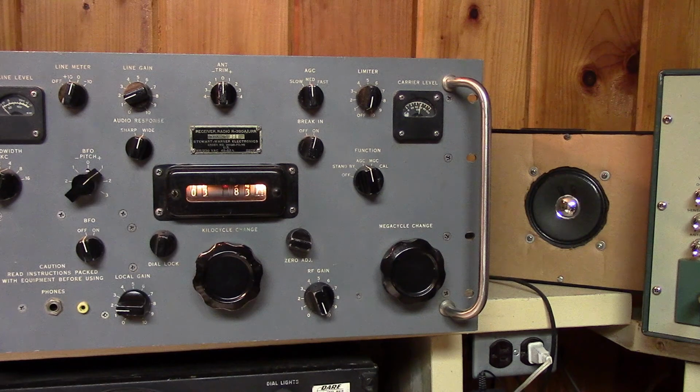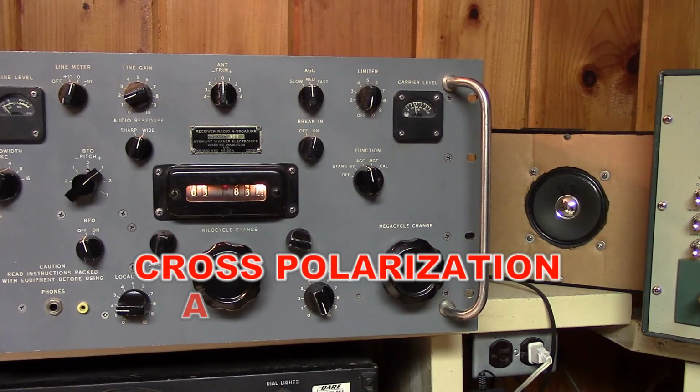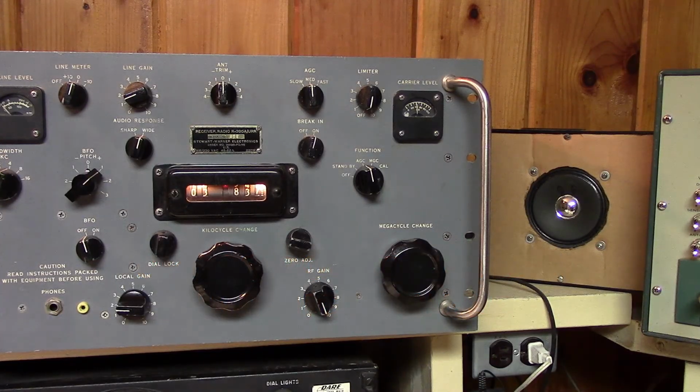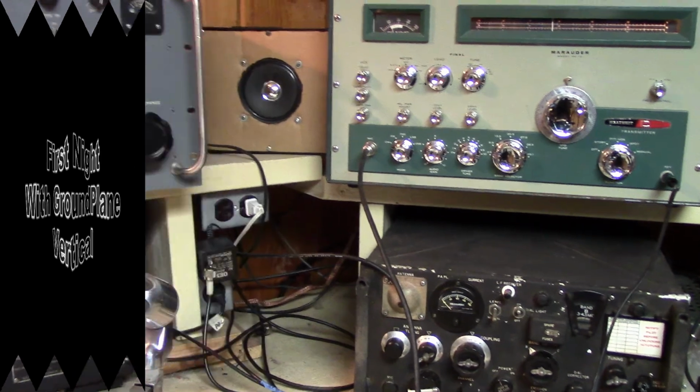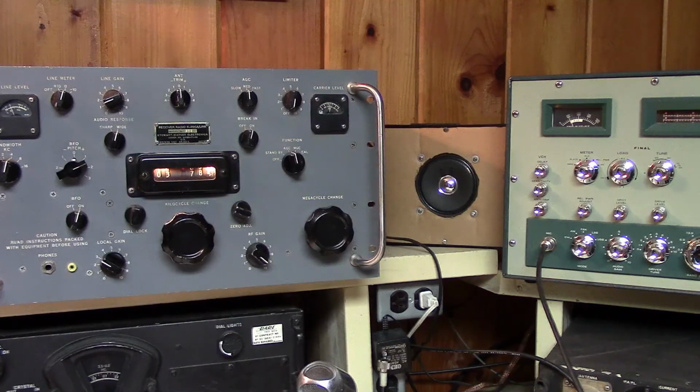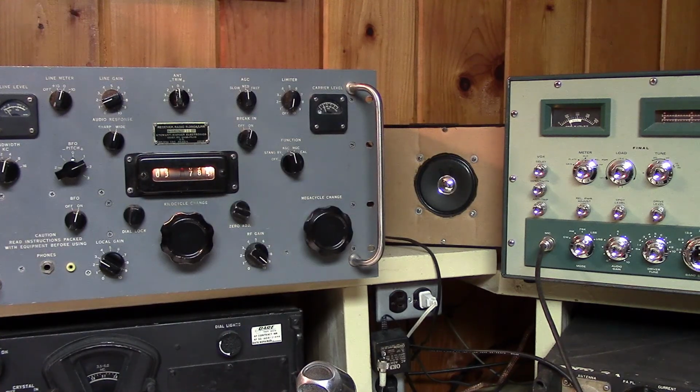So we're going to go from the dipole to the vertical. Very little energy coming in on the vertical, which tells you that it's not ground wave. This is near vertical incidence signal. And back on the dipole. So England is really coming in on that vertical. They're saying it's 10 dB hotter than the dipole.